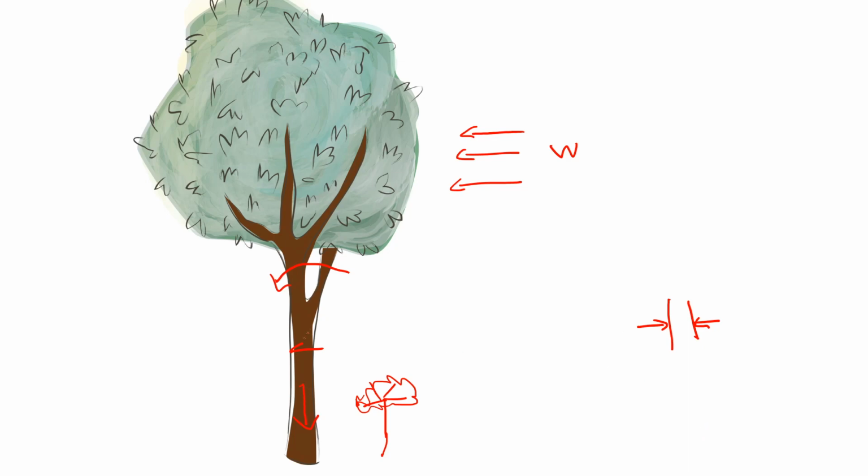And what about tension? Well, a tree does need axial strength in tension, because if you have layers of a tree like this in a tree's trunk, in order for this thing to carry bending moment from the wind force, some of the fibers must go into compression and some of them must go into tension. That's what's going to provide the couple and thus the moment resistance to resist the overturning moment produced by wind and other lateral forces. So because of that, in order for the tree fibers to go into tension, they need to have a large amount of axial tensile capacity.